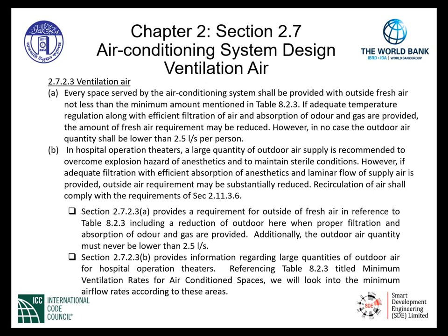We will find that there are a series of calculations that have to be made to determine how much outside air needs to be provided in a mechanical ventilation system. So we need this initial requirement as a basis for our design, installation, and final balancing of the system for verification.